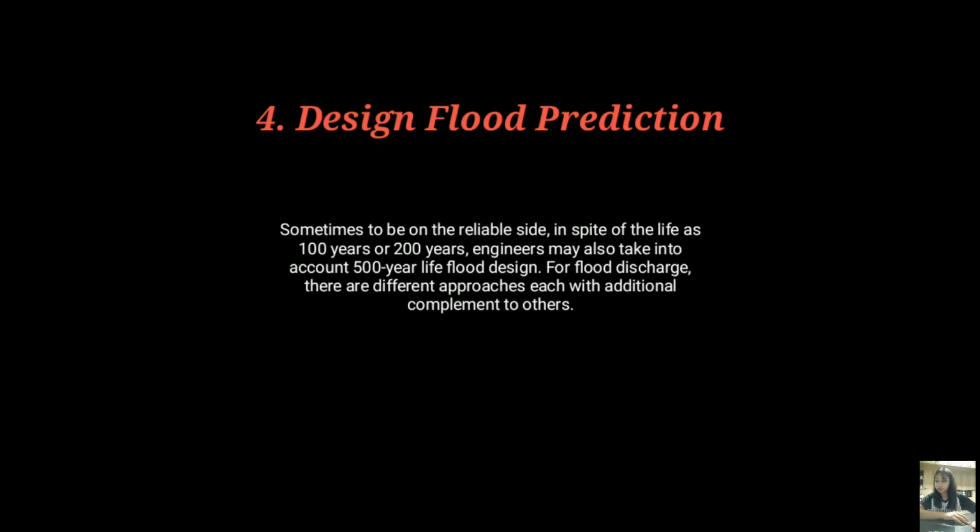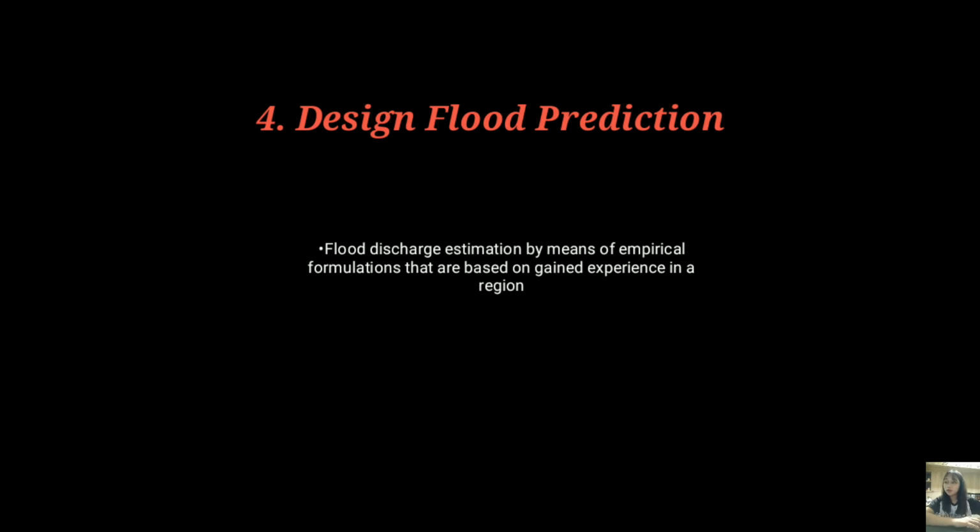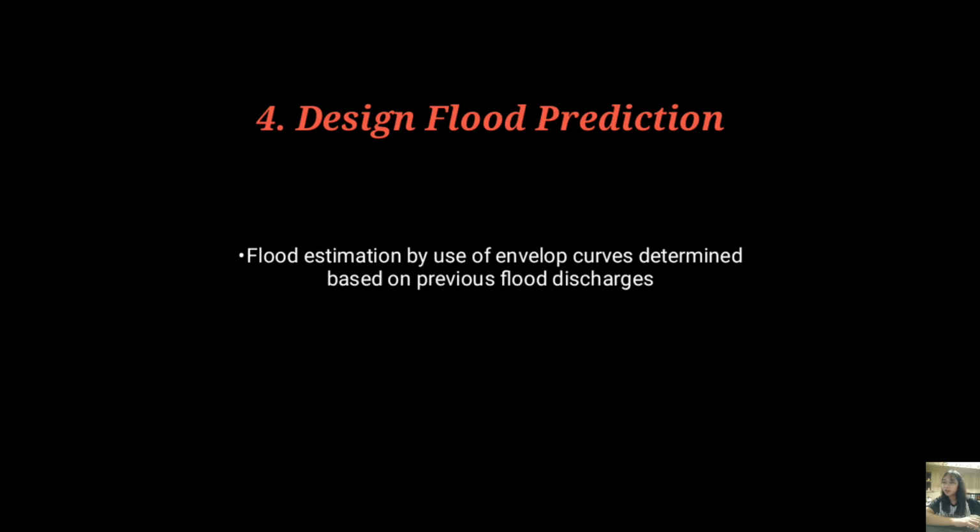For flood discharge, there are different approaches, each complementing the others. Flood discharge estimation by means of empirical formulations that are based on experience gained in a region. Flood estimation by use of envelope curves determined based on previous flood discharges.